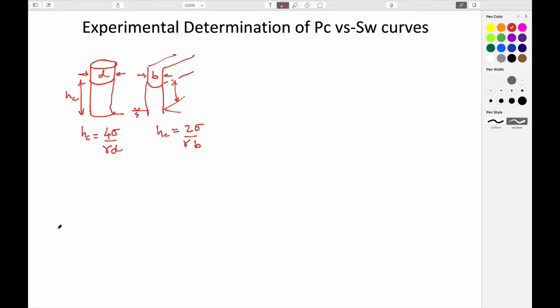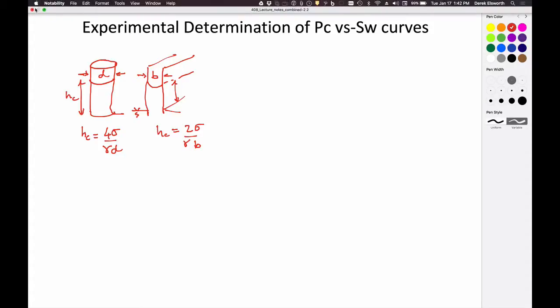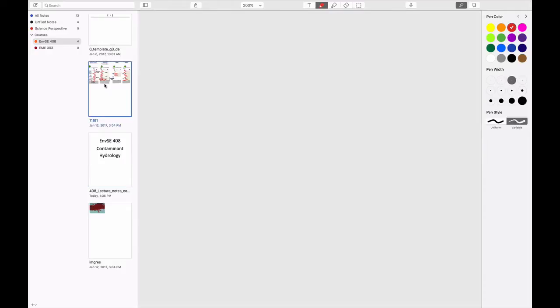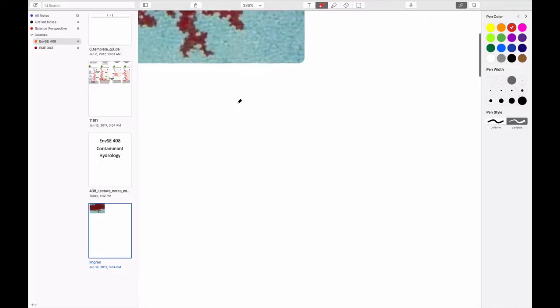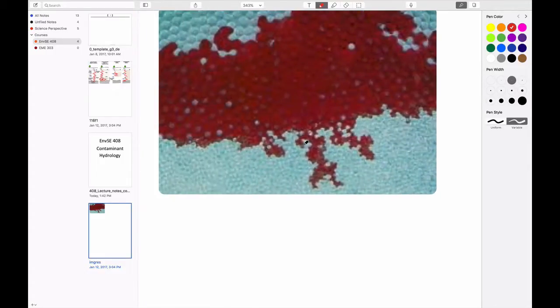And we did that not so much because we're interested in how much it rises when you put a capillary in the fluid. We're much more interested in the idea that if we had a fluid sitting in a porous medium, we'd much rather be able to figure out exactly, for instance, what height, if you imagine this as a tube sitting here, what height of fluid giving you a pressure at this particular location allows this to go down here. That's basically the geometry that we're interested in.